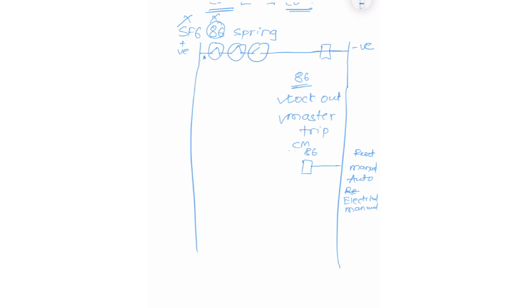In which you will push a push button and then the lockout will reset. So how will this lockout relay operate? It can operate through an NO contact, which can be our overcurrent protection like 51N. Whenever our relay operates, this particular contact will close, which will make a coil inside this particular lockout operate, which will pull up a plunger, and the contact inside it can operate.